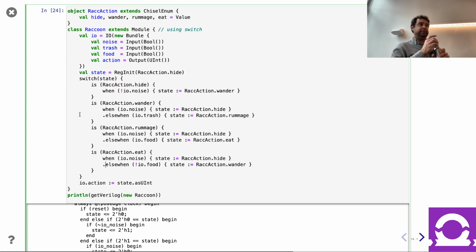So I'm not familiar with the BlueSpec state machine library, but no, there's not, to my knowledge, a state machine builder inside of Chisel. One of the things that's interesting is when you start really imbibing the agile hardware design philosophy in Chisel, you have state machines, but they tend to be more implicit and simpler. I think a lot of times when we spend a lot of time drawing transition diagrams and having really clear arcs and that kind of stuff, that's a bit more of a waterfall style philosophy. Sometimes you have a much more implicit state machine with the agile philosophy.